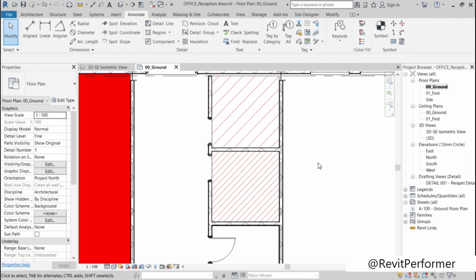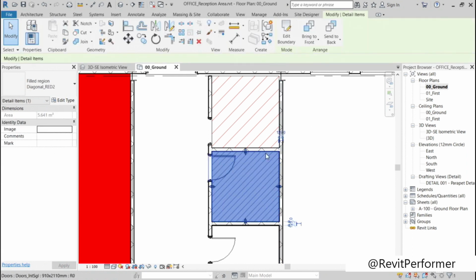So, for example, your walls might change positions on your linked CAD file, and you want these walls in Revit to change, but you also want the filled region to change. And the benefit you've got there is that filled region is completely editable and easy to manipulate in Revit, rather than try and go into imported categories and change the linked CAD file and so on. You can do that in Revit straight away using your fill regions and your edited fill patterns. That's why those fill patterns are really useful in Revit. Not only are they great for highlighting areas in a floor plan, but they can be adapted to suit previous AutoCAD standards.